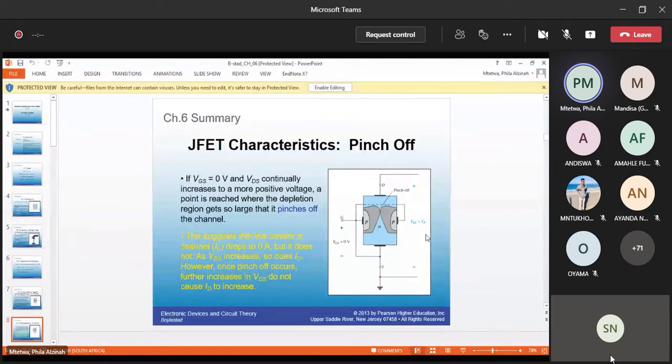It's been pinched, it's twisted. Once it's twisted, that kink causes the channel to be narrower, and hence water cannot flow. So with everything else connected, we avoid this situation. This is pinch-off voltage. Here, the depletion regions have come too close to one another, narrowing the passage, so you cannot get current to flow through.